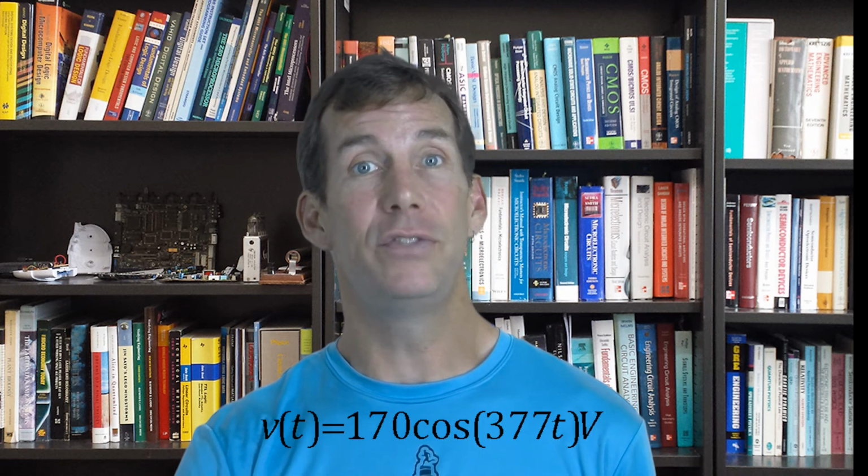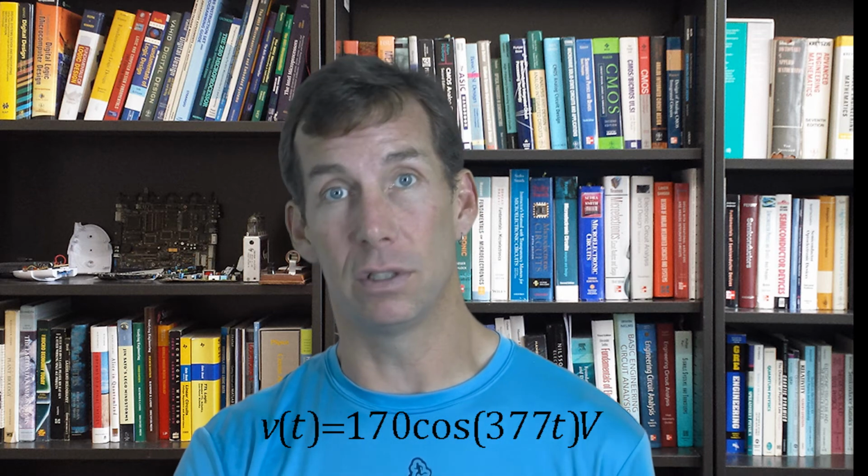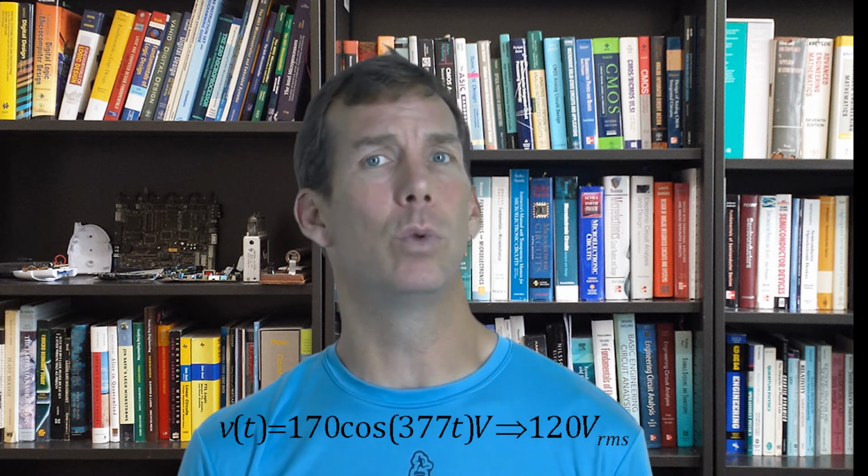The actual expression for a 120 volt RMS 60 Hz voltage is v(t) = 170 cos(377t) volts, but it delivers power as if it were a 120 volt DC signal. Here we have the average value of an arbitrary function x(t), in which we have made x(t) equal to an arbitrary cosine wave with no phase shift.